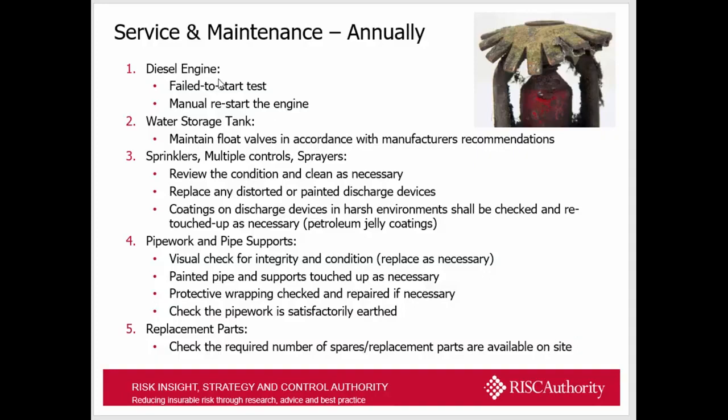Replacement parts: there should be an adequate number of spares or mixture of spares applicable to the hazard classification and the correct sprinkler spanner for the heads. And there also should be an adequate number of spares that come with the pumps.